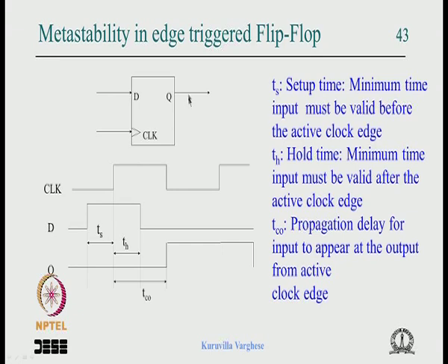So it means that you are not really sure what the output is going to be. It could be 0 or 1, but as I said, normally it is not a dangerous situation as long as the input persists for at least 2 clock periods, then definitely in the next clock edge everything will be okay, because it will meet the setup and hold time, and then the data is captured at the output properly.